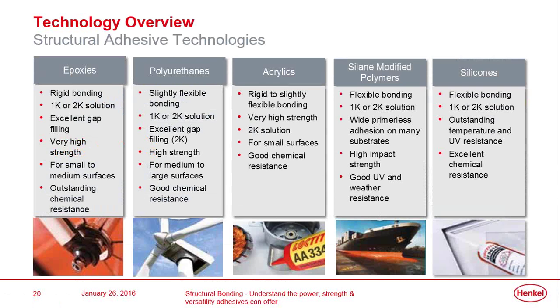So the adhesive types, as I've sort of shown before, we have things that vary from semi-rigid to really flexible and highly stretchy. Now, if we look at some of these families from left to right, we're going from highly stiff to very flexible. And they tend to mirror the applications that they're being used for. So if we're bonding bicycle forks, for example, and we've got titanium and composite, then clearly they're taking a lot of load. They need to be high strength.